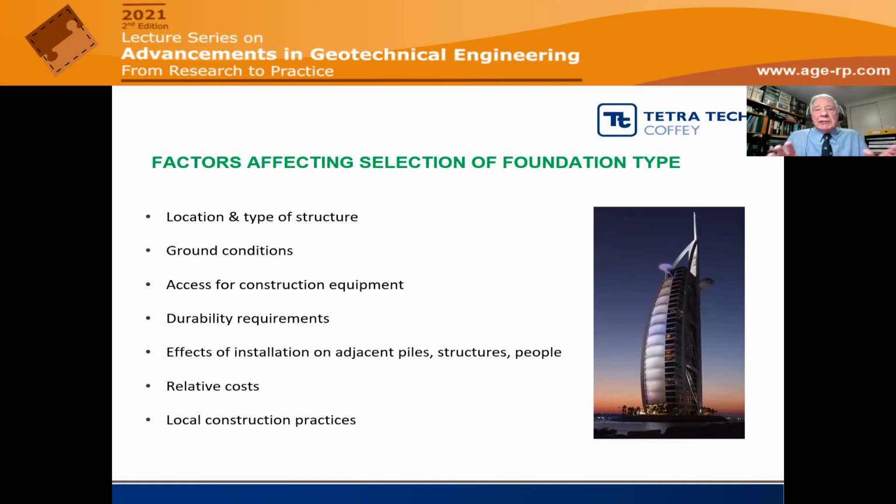We need to make sure that our construction doesn't adversely influence adjacent piles or foundations, adjacent structures or people, because there can be noise problems, for example, with driven piles. And of course, relative costs relate not only to economics, but also to sustainability. And finally, local construction practices that clearly, if we try and introduce a type of foundation which is totally unfamiliar in the location of the project, we may be asking for problems.